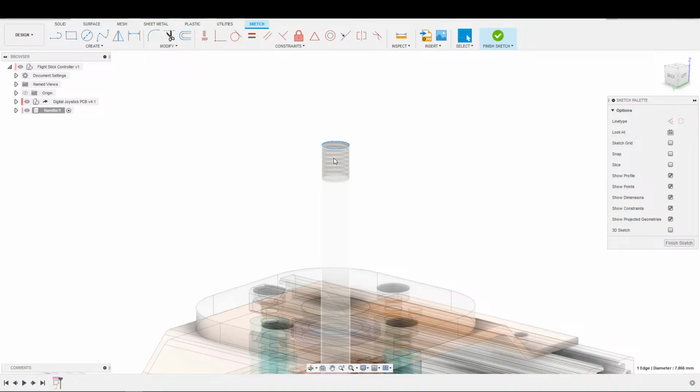So basically, I'm going to want to thread a portion of it, and anything below that portion actually needs to be a wider diameter just so it does not interfere with the threads. So we'll go a little bit below the threads and then open it up below the threads so that it is loose. And my battery is nearly dead on my calipers.